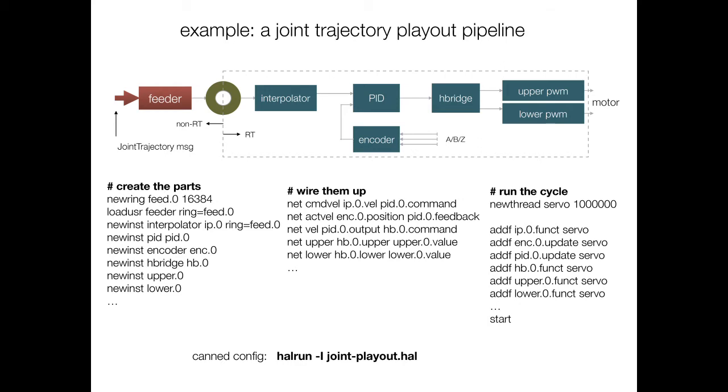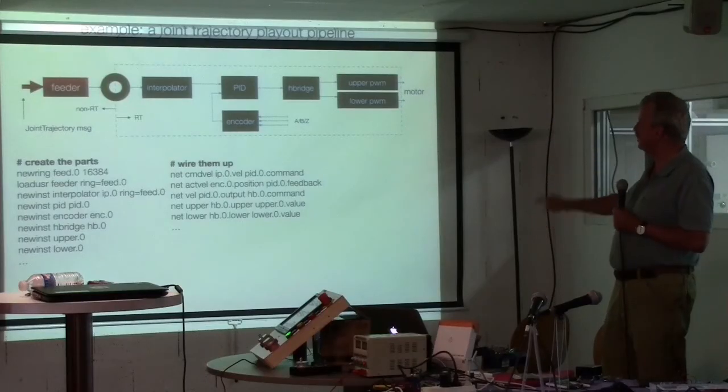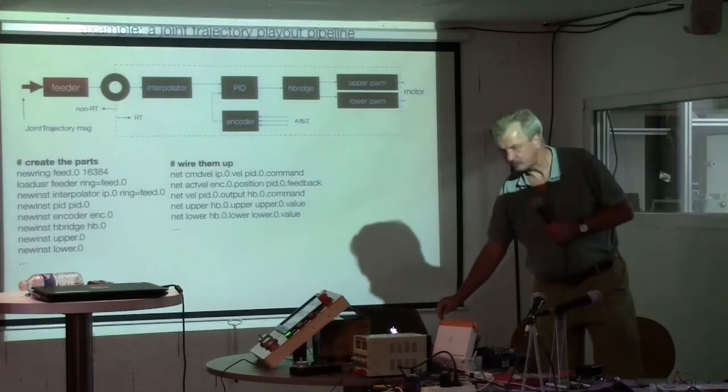And you can connect one output to any number of inputs, but you better not connect outputs against each other. Okay, that's the same thing in this language. This is very close to a hardware setup. So you instantiate all the objects, you stick them into your breadboard, if you will, then you wire them up, and that defines the lines between these components.